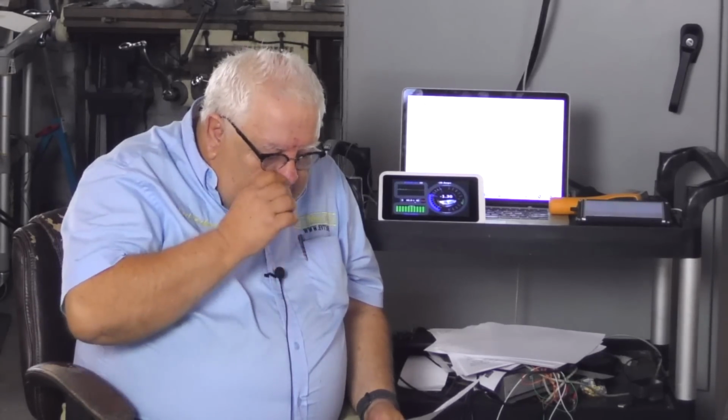So you can't really escape I²R losses, and it's a very cruel reality of electronic design choices, and 48 volts DC as a solar energy storage medium is just a famously poor choice, and it's because of I²R losses. Let's reverse the whole problem and produce 10 kilowatts of power from the system.